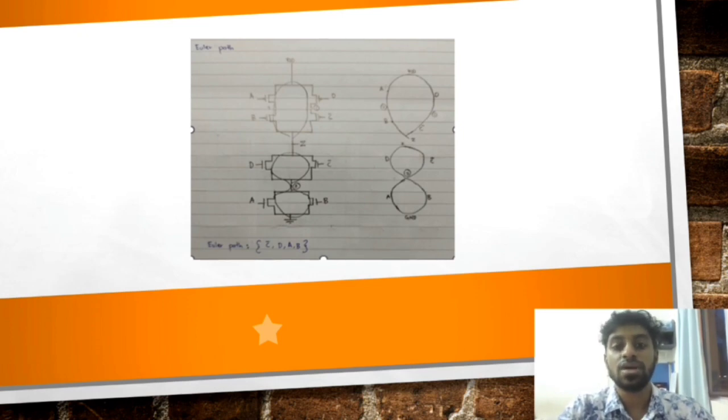The path should be chosen where the path goes across each of the transistors. The Euler path is important because it is used to minimize the size of the layout. In this way, we can construct an efficient layout.